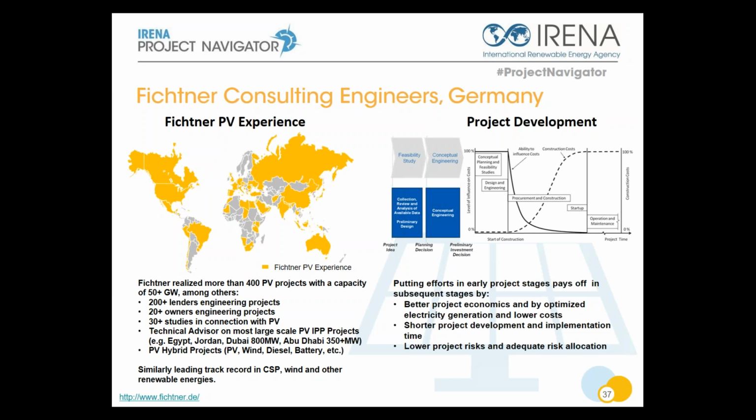Sometimes it's not only difficult to comply with the requirements, for example with regard to primary and secondary reserve, but even the grid code requirements can be set in a way that they destabilize the grid. For example, low voltage ride-through requirements combined with a requirement that the PV plants have to switch off at a certain voltage level, say at 10% of the nominal voltage, so that after fault clearance the PV plant would often destabilize the grid operation.